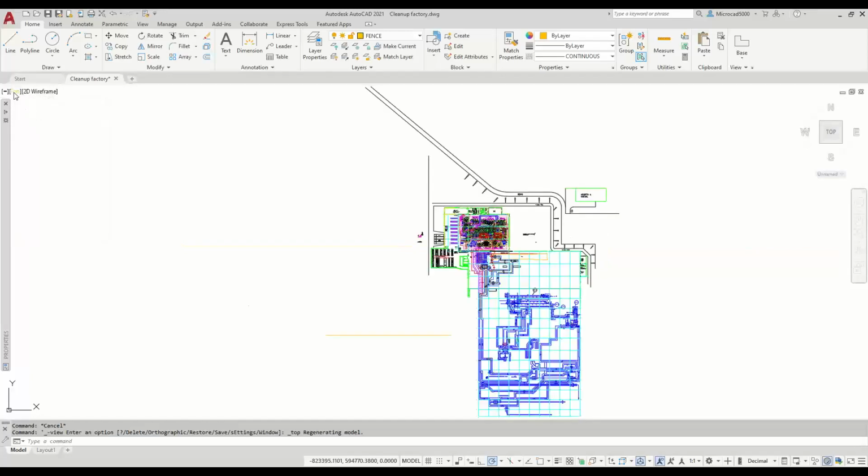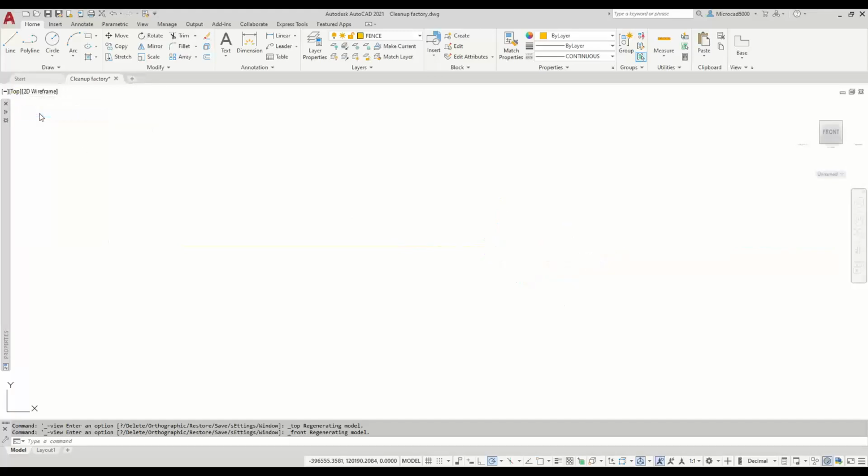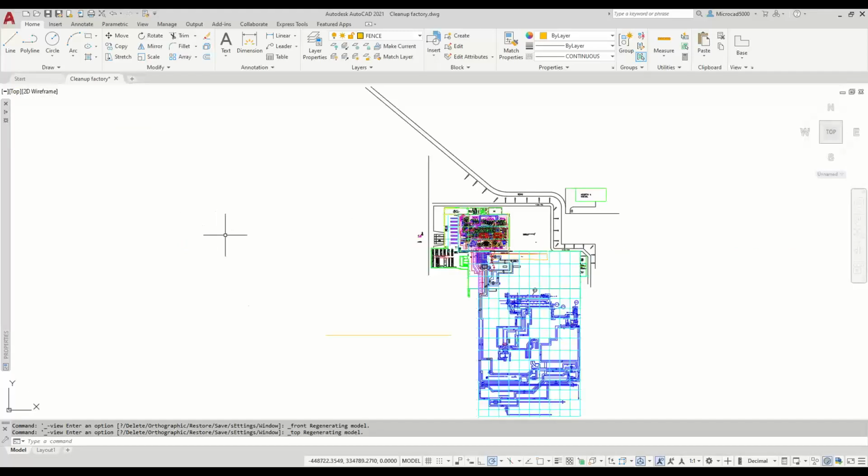And then if you're using the full version of AutoCAD, keep an eye on this UCS icon. If I do a front view, look what's happened. It's automatically turned around your XYZ coordinates. So if I now did a flatten on these objects, it would push it all to the edge of the sheet of paper. You would just trash your drawing file. So what you need to be careful of in the full version of AutoCAD is doing a top view. And to be fair, I'd recommend you doing it in a top view in LT as well.